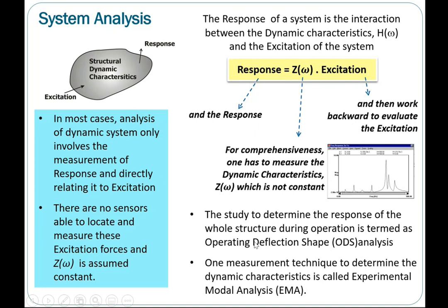With these two pieces of information, with ODS, you know exactly how high your vibration is over the entire machine, not only at the four bearing points that you learned in CBM. In this case it is the entire machine.